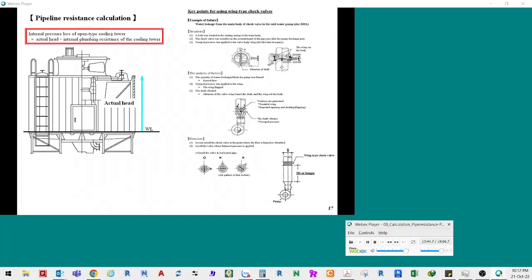Calculation of resistance for open circuit scenes such as open-type cooling towers requires the actual pump head. Biased flow causes trouble including increased resistance, performance deterioration, and damage to equipment. It is important to run the fluid as smoothly as possible. Reflect minimum requirements, including intervals between the pump and other resistance elements such as valves and elbows, during construction. If you find any improper spots on drawings or in construction sites, take appropriate actions.